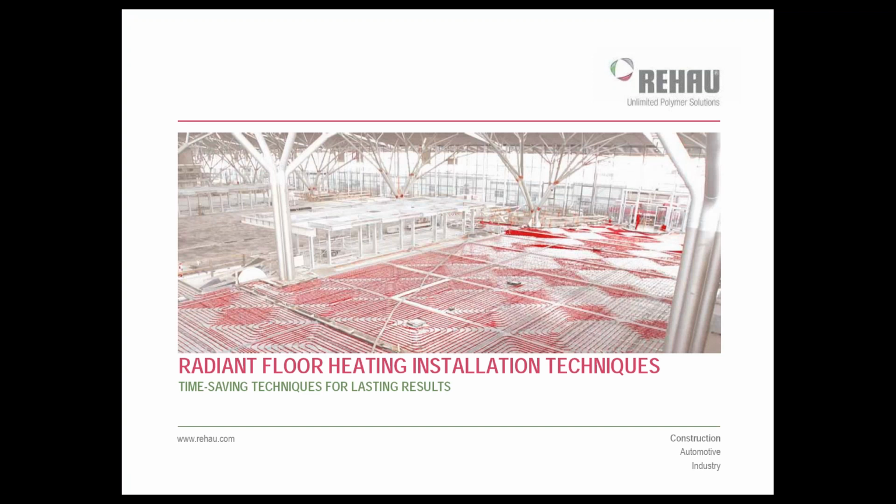Real quick, I did get one question come through. In the carpet applications, the pad also makes a difference. Yes, absolutely. The pad would certainly add to the insulation value. We're going to be showing, I think coming up, I have a little slide showing a cross section of it. But yeah, anything that you're putting on top of the radiant or between the radiant and the space is going to certainly increase the insulation and then decrease your output. So it's something to definitely consider.